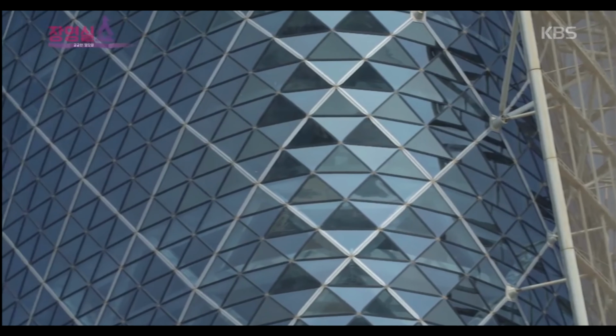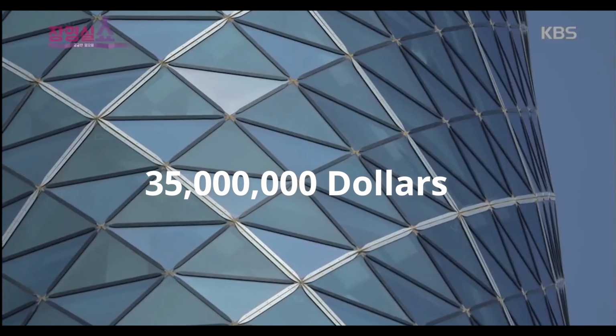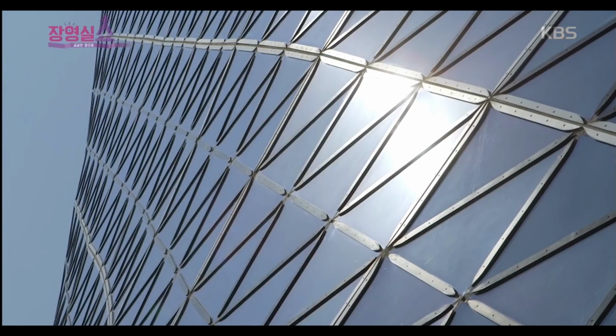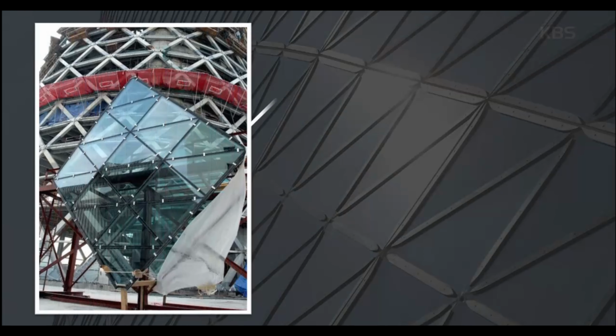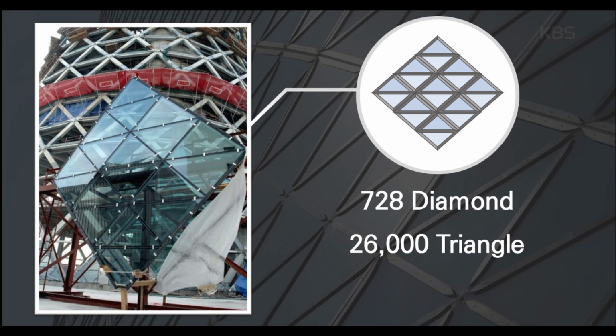Even with this relatively cheap method, it was still a highly expensive project with a budget of $35 million. Consisting of numerous glass panels, you can see that many different diamond units organize the twisting facade. This diamond unit consists of 18 glass panes, and to make the twisting facade, 728 diamond units were needed. It means there are a total of about 26,000 triangular panes, weighing 46 million pounds, about 2 times more than the total steel used in the building.